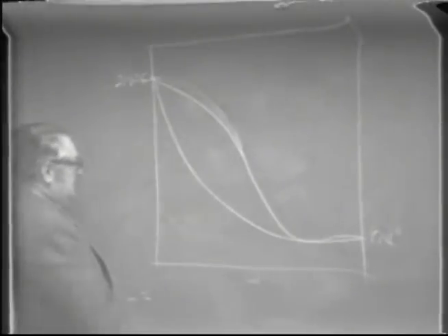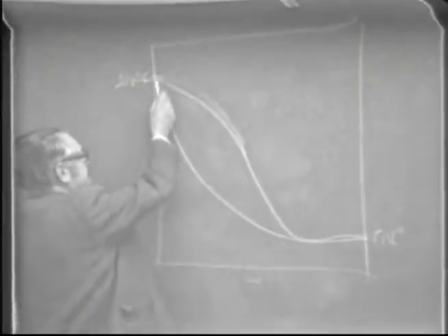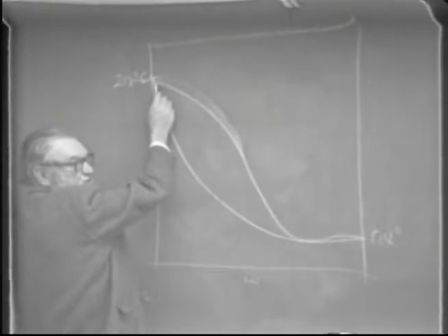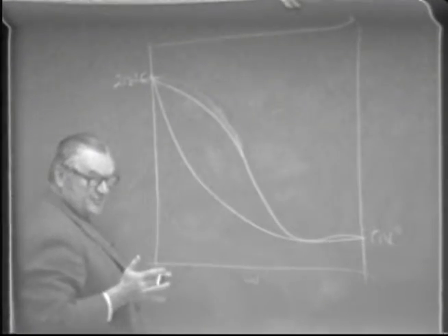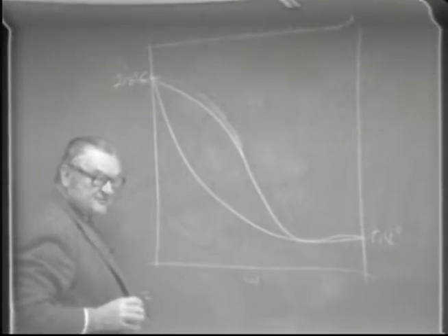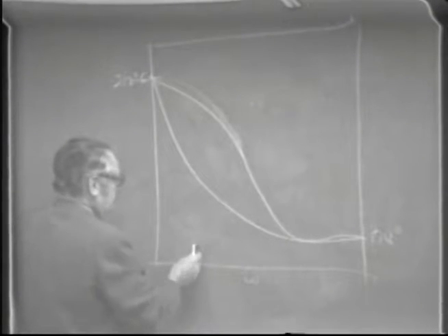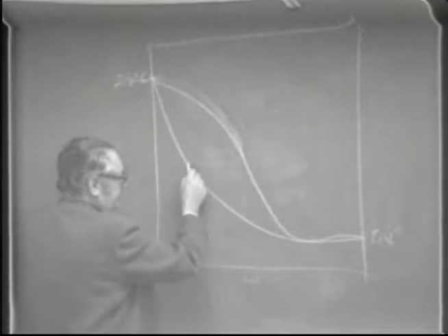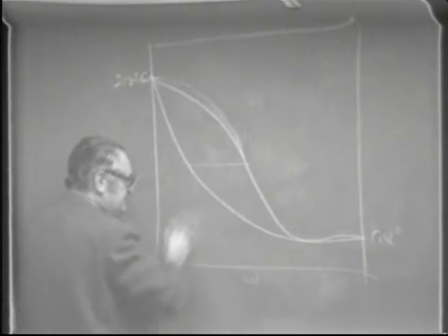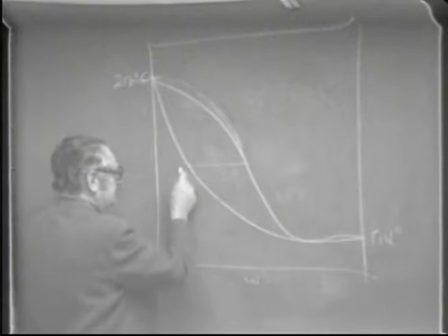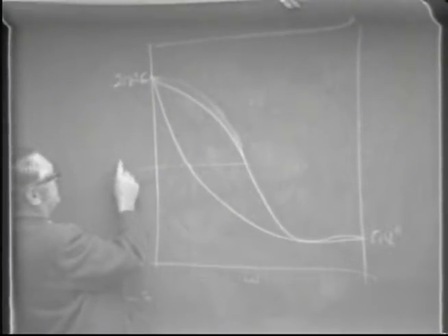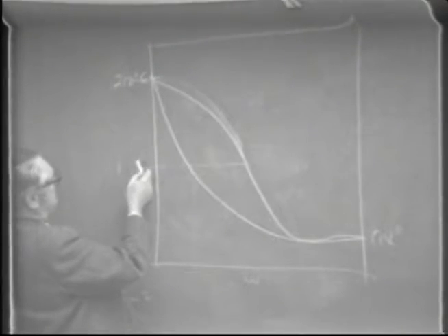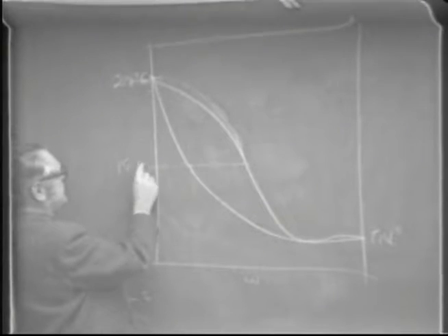And of course, down in the stripping section where you have very small steps here, because you're up in this corner here, the temperature is going to read about the boiling point of water, maybe a fraction of a degree lower. In the middle point of the column, you get this maximum change here. So if this was a temperature here, maybe 174, 185, let's say this is maybe 182, something like that.